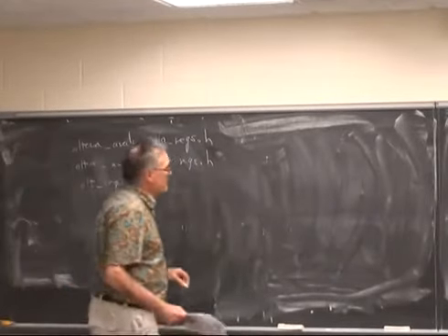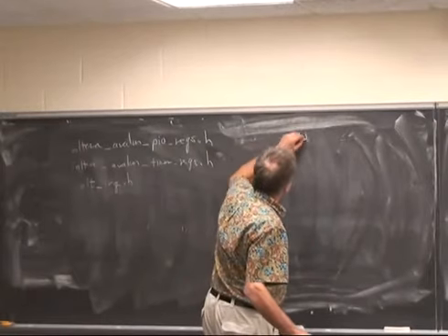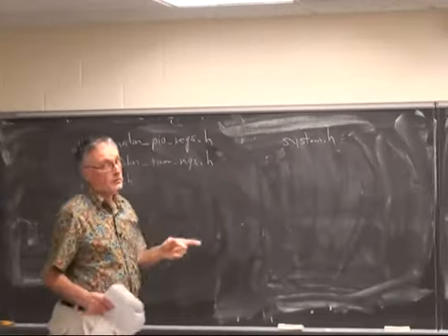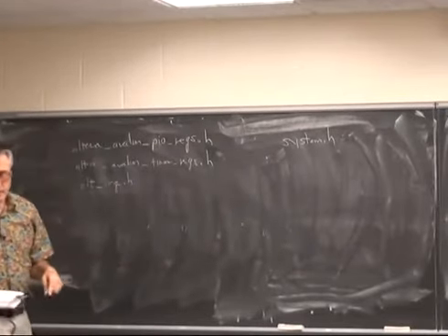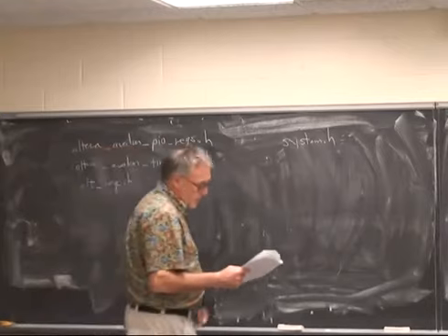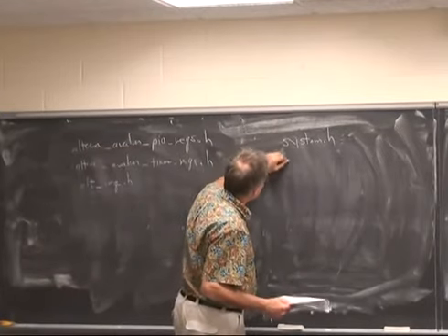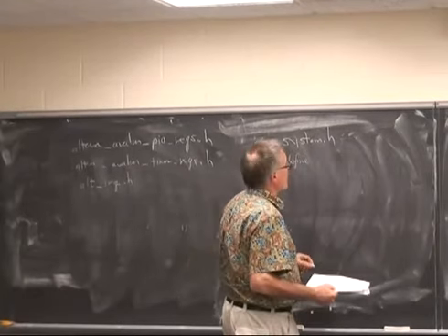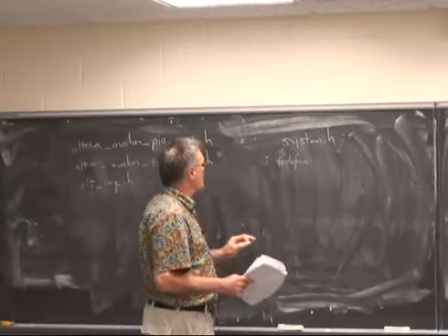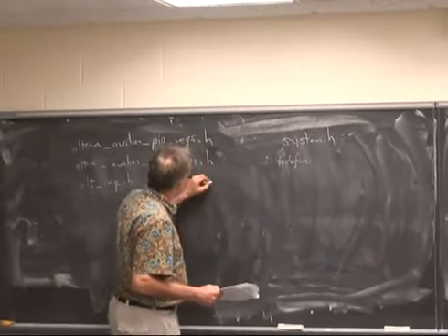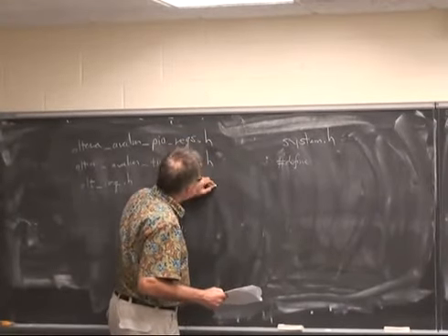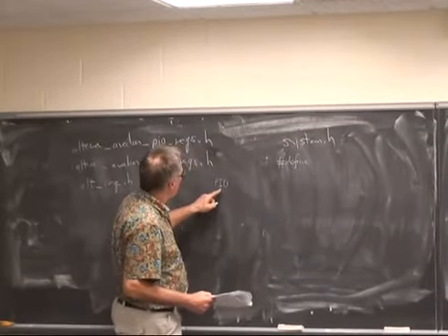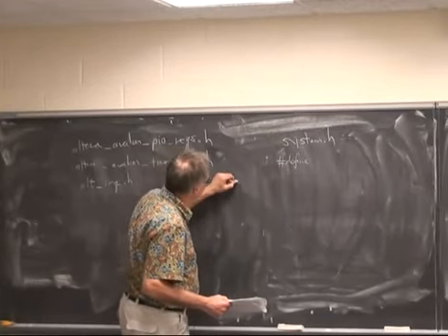As an example of what's in system.h, again, this is generated by SOPC Builder for your viewing delight. There are a bunch of defines in here. Now, let me just step back and say that in SOPC Builder, I asked for a parallel I/O port, PIO port, whose name is switch.